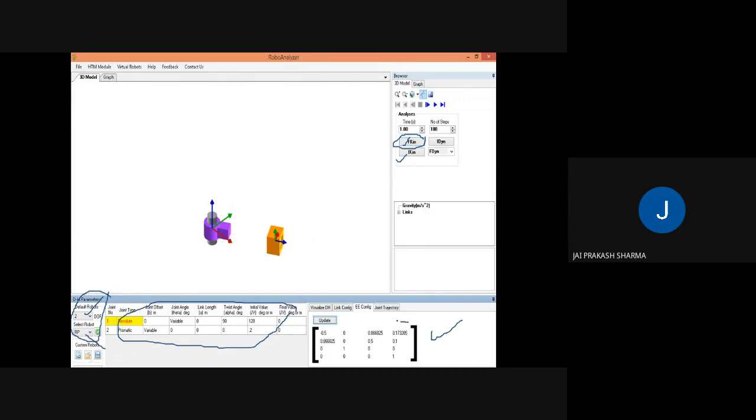Okay, so what it actually tells us is the final position of our end effector, by making these changes in the link rotation or translation with respect to a prismatic joint. In such a manner, if you are going to create a robotic arm with the help of this software, you can find the final accurate tool position of your robotic arm.